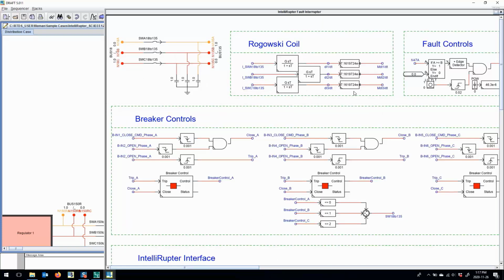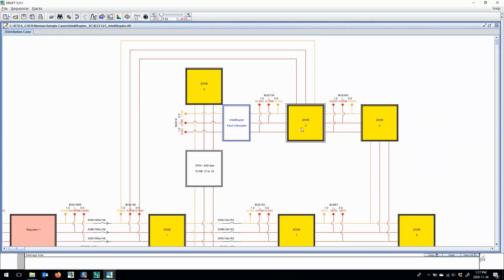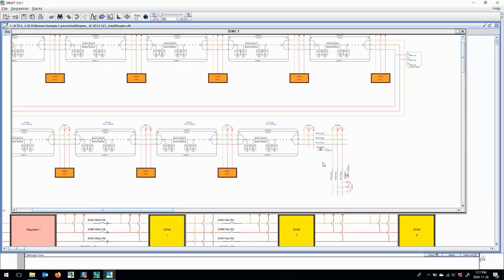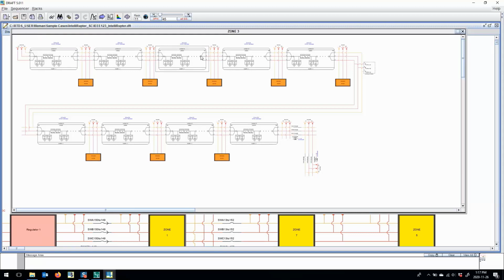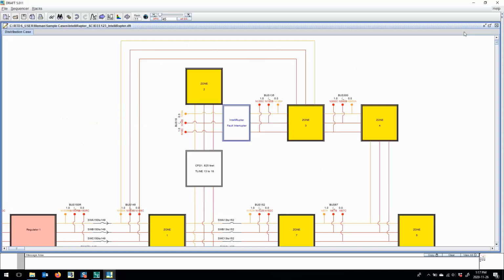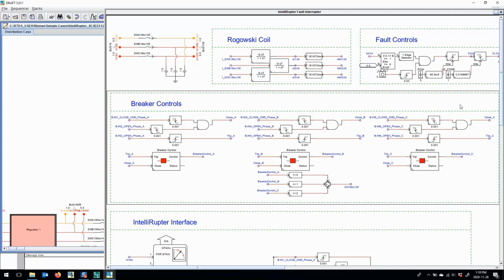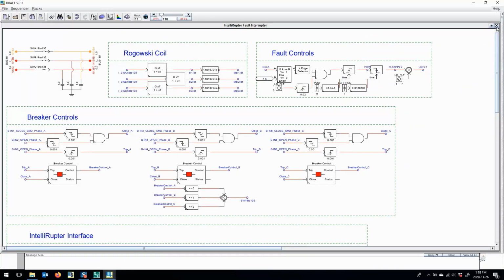So one more thing I could add here is, we have a breaker here, and then we have this zone 3 feeder where we have a bunch of lines and loads here. And then this breaker at the end of the feeder is normally open. So we have a radial feeder here with a bunch of lines and loads. Now, the lines all have inductance in them. And what happens is when the breaker operates, we suddenly interrupt the current that's flowing through those inductances. And that can lead to what's known as chatter. Okay, so this is a numerical oscillation that can come from this type of simulation.